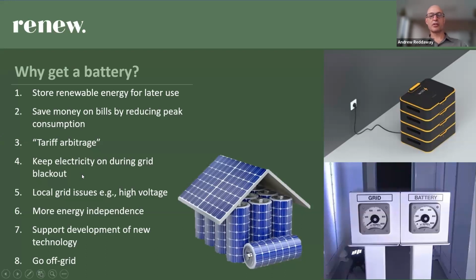Keeping electricity on during a grid blackout, you have to be a little careful with that. Not all battery systems have that capability. It depends not only on the battery itself and the specifications, but also on how it's installed. So if that's what you want, then you have to really check with the solar installer and retailer that all those components are in place.